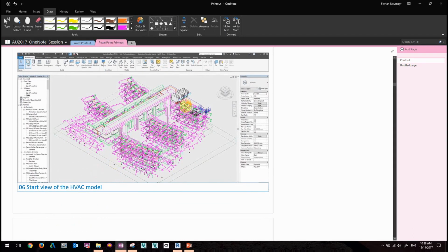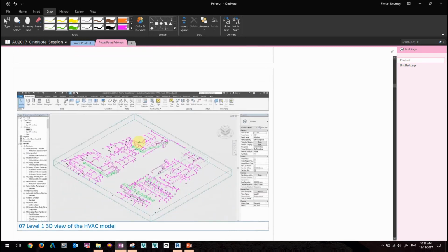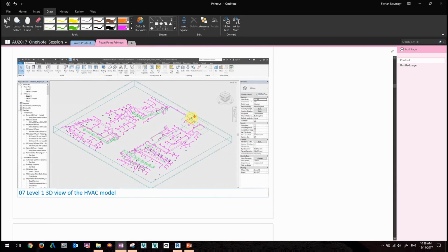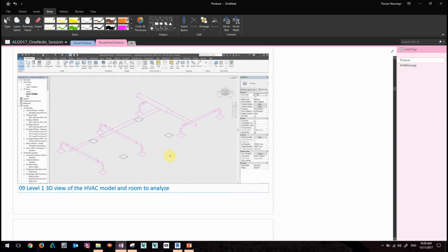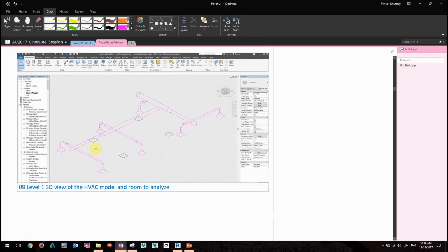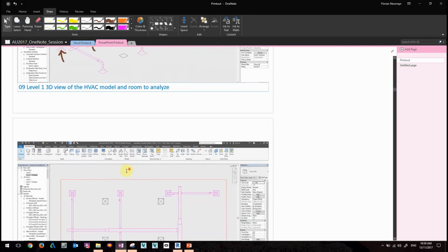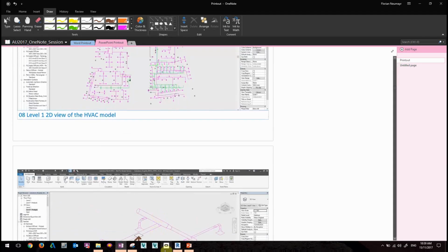Good. We know in this model that the HVAC model has been linked in. So I have just added this on to the HVAC model, where we can then prepare. And in CFD later on, we make use of our surfaces to set up our boundary conditions. So that's our first stop.